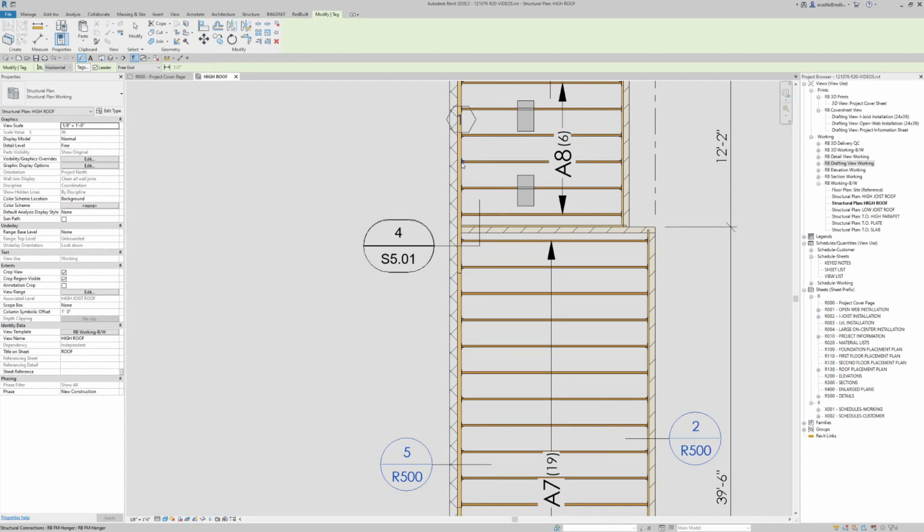So hangers will have the hanger symbol, beams as joists, ledgers, or glulams will have the rectangle. So once we hover over and have it, we'll pick and select and place it. And you can make small adjustments as you need.